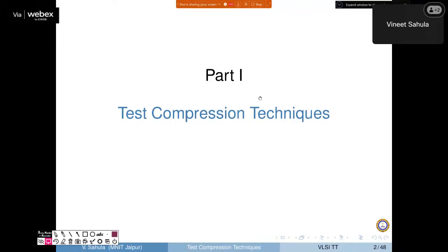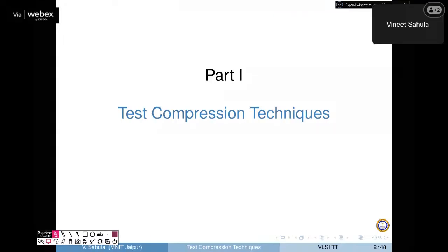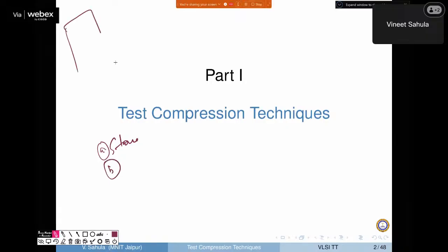Okay. So we are looking for the test pattern generation or storing the input patterns. So part A is storing patterns. Part B is if you are applying some random patterns only, some 1% or something of the total of whatever is the exhaustive test pattern, we can generate that.